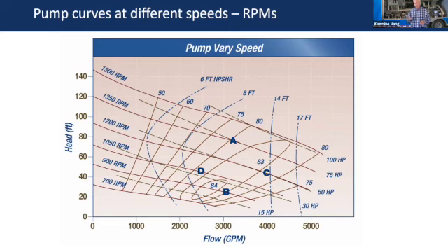And so the old standard was you can only run half speed. So if 60 hertz is approximately 1775 RPMs on a lot of pumps, they vary a little bit from make, but on a vertical turbine, a basic pump, if you're at 1700 to 1800 RPMs and you slow it to 900, that's half speed. That would be going from 60 hertz to 30 hertz. That is usually to make sure you don't void the warranty on your motor. You may have to have that limitation. However, I'm going to point something out here in a minute, how much less horsepower you're pulling. And maybe if you get it down that far, that should be enough anyway.